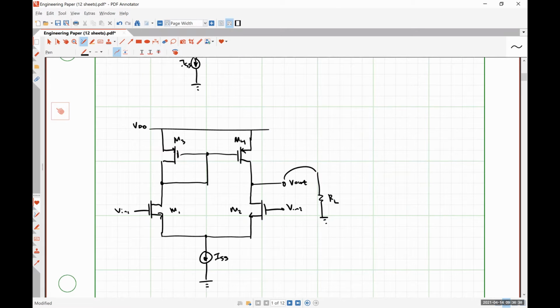When we increase our voltage in VN1, we are going to cause our current mirror to draw more current, which is going to get copied. So if the current in M1 increases, the current in M3 must increase, which in turn mirrors in M4. And so we see more current available to flow through that load resistor RL. So in both cases, both current paths serve to increase the current flowing through our load resistor, therefore increasing our voltage output.